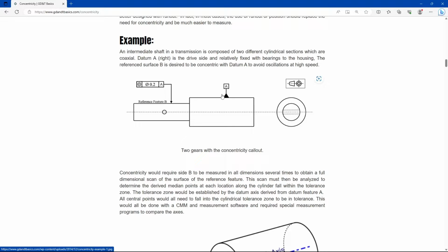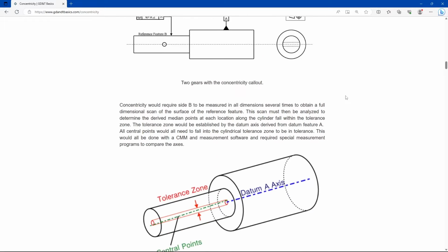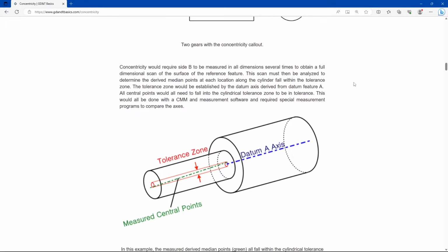And in theory, the way that we measure this is we have a tolerance zone over the axis. The problem with concentricity is we need to actually touch the points on the outside of the feature. This fundamentally has to be a cylinder because the circles are 2D. So it can vary depending on whereabouts we measure, and this alone means that concentricity is theoretically impossible to actually measure.